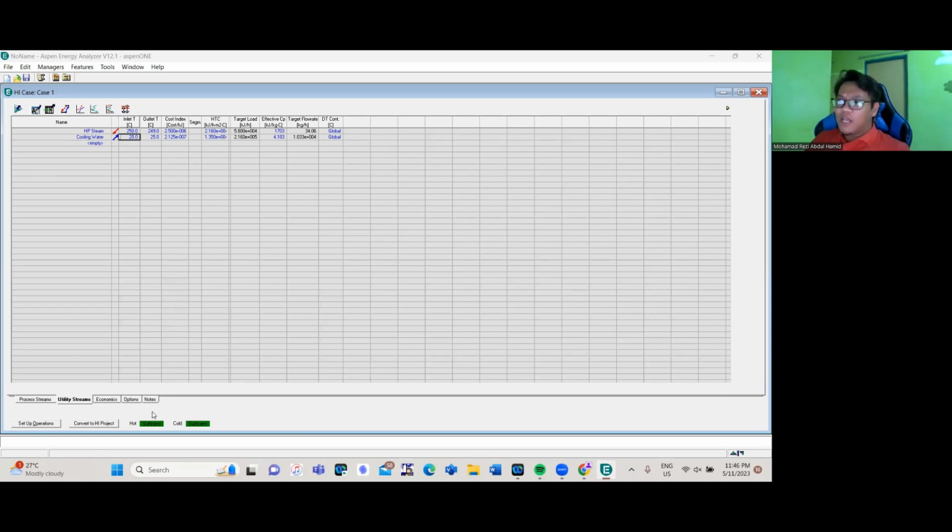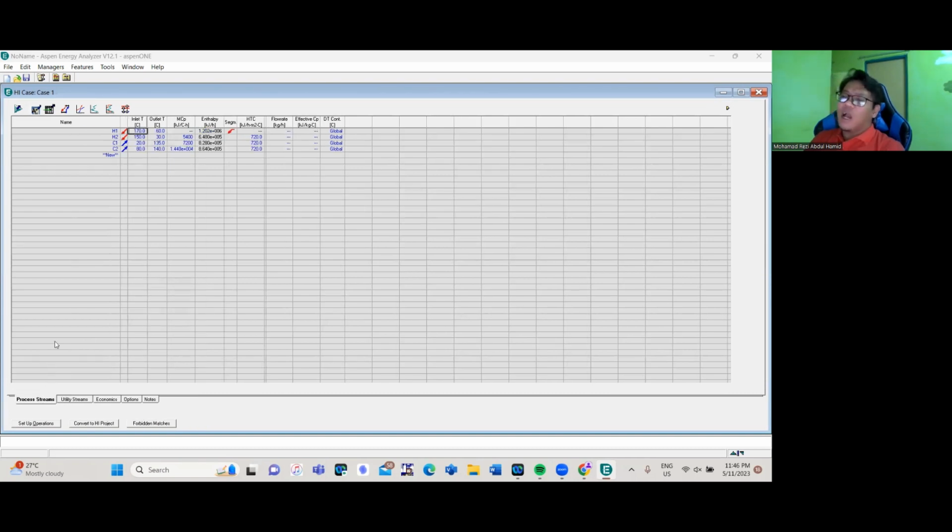Now, as you can see, the red one turned into a green one, meaning that if you specify this, the process stream along with the cold and hot utility will be sufficient to achieve your target final condition. Now I'm going to go back to process stream. Before that, one important thing I would like to highlight is, as I said, you are currently creating a new case.